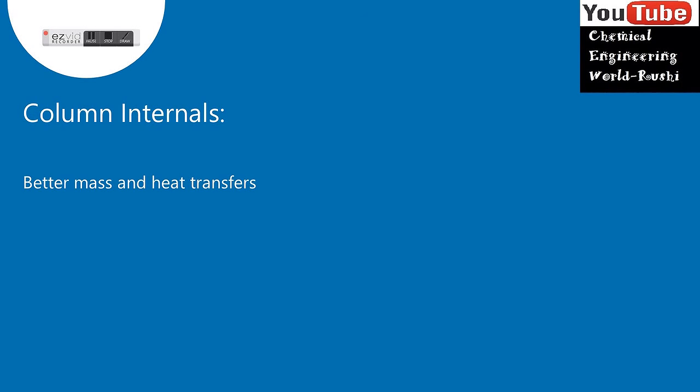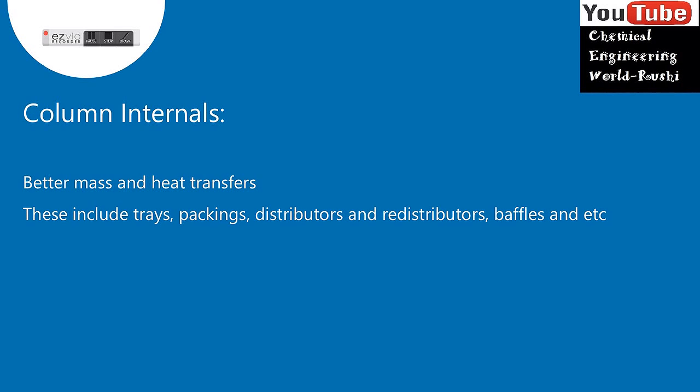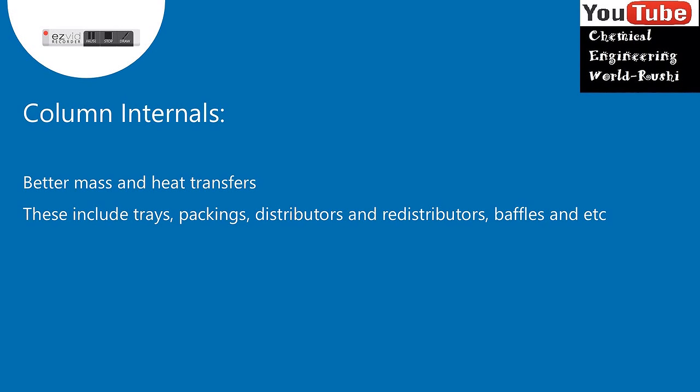Next important part is column internals. Column internals are installed in distillation columns to provide better mass and heat transfer between the liquid and vapor phases in the column. These include trays, packings, distributors and redistributors, baffles and so on. They promote an intimate contact between both phases. The type of internals selected would determine the height and diameter of a column for a specified duty because different designs have various capacities and efficiencies.